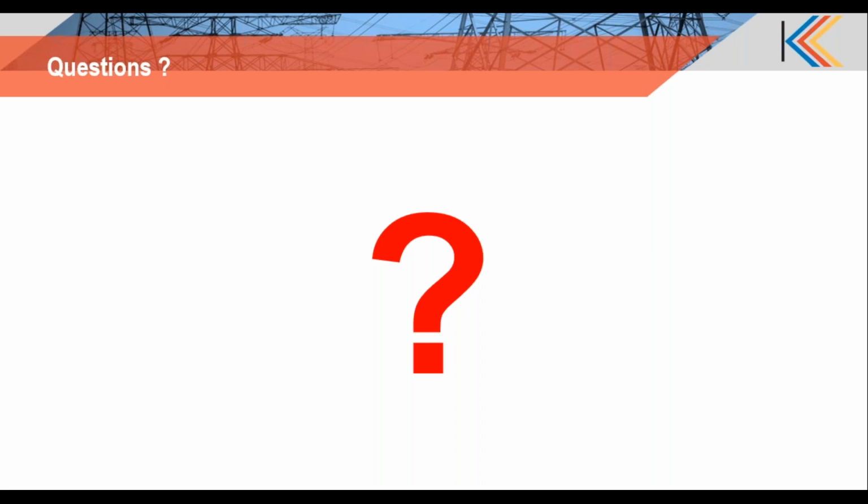One is about reroutable GOOSE, or R-GOOSE. Seems interesting. Can you share some real life examples of R-GOOSE which is being used currently? Yep, R-GOOSE is basically using the same functionalities provided by the 90-5 that's primarily intended for your phasor measurement data transport across different geographical locations. But R-GOOSE has been used for some interlocking.